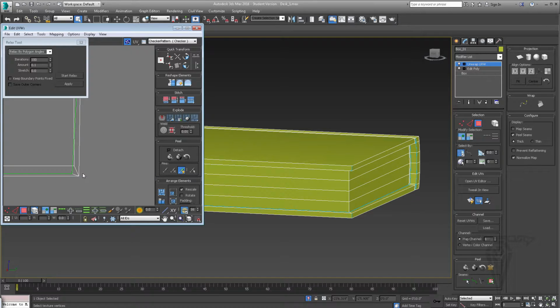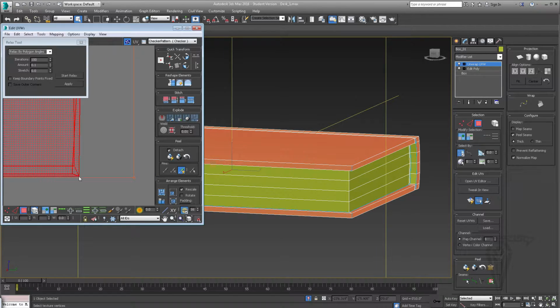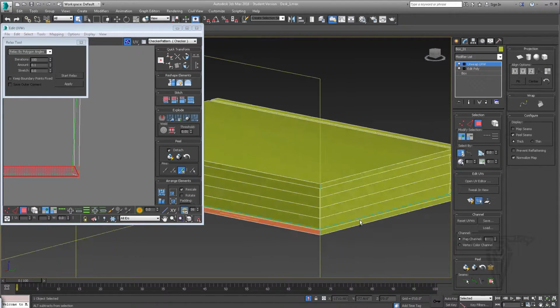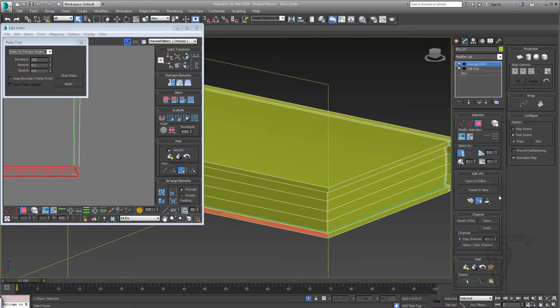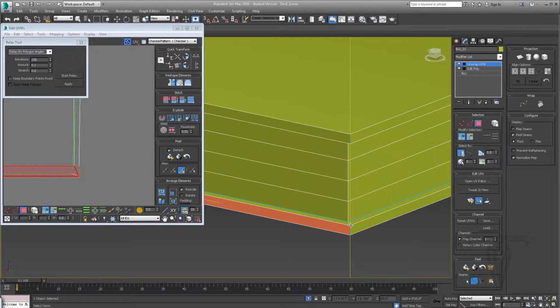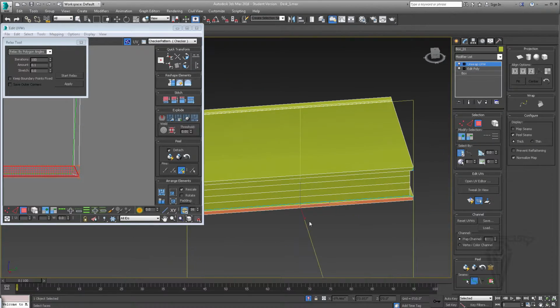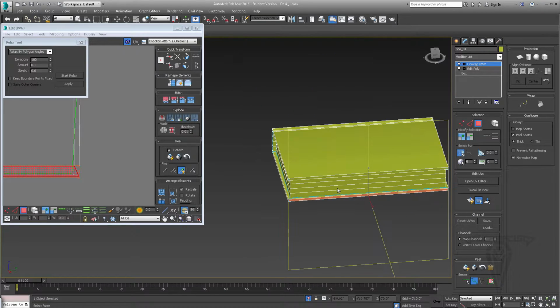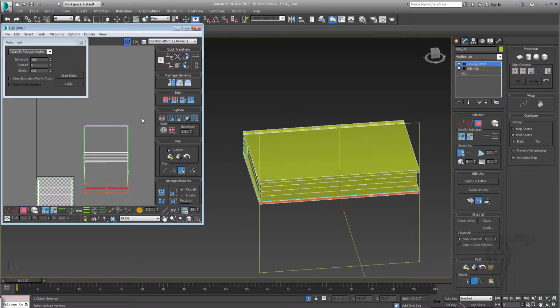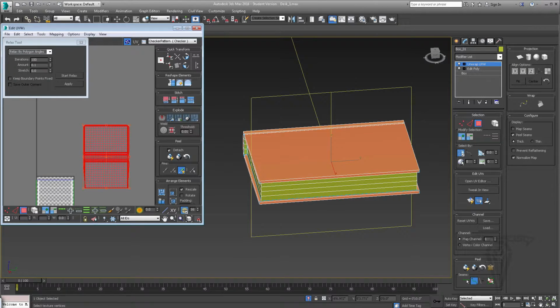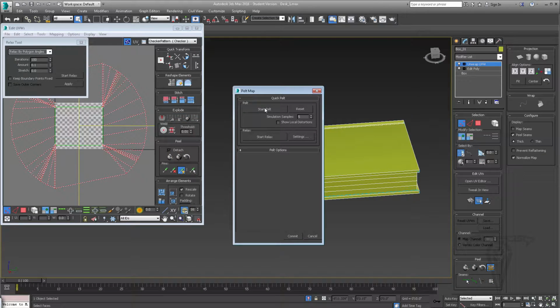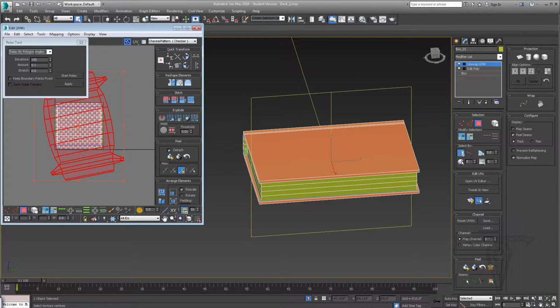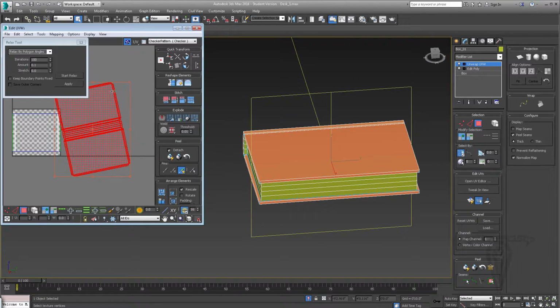And it looks like I might still have some kind of issue going on over here. Let me turn off element mode. Yep. So I forgot to do that to the bottom as well. So this is the problem. This is me showing you how to problem solve, because I've actually not done this part of the tutorial so far. So you're seeing how I actually unwrap my stuff, pelt, start pelt, commit, start relax, and I think we're good finally.